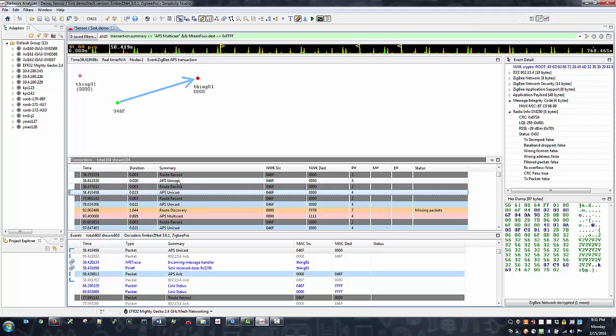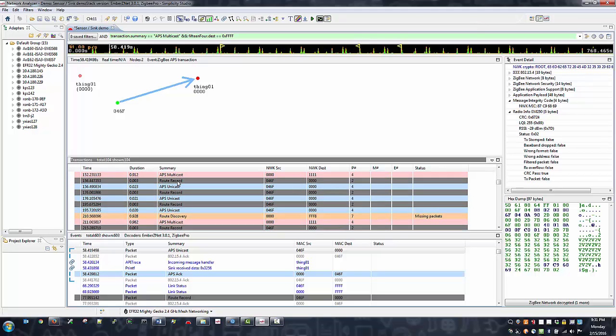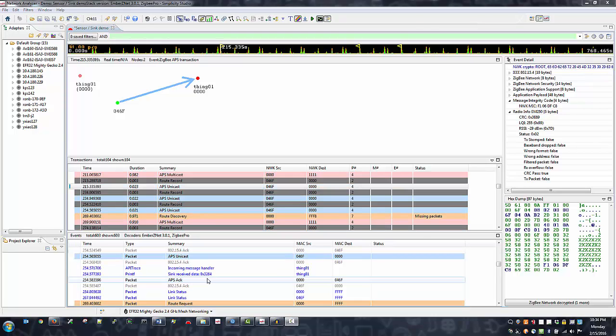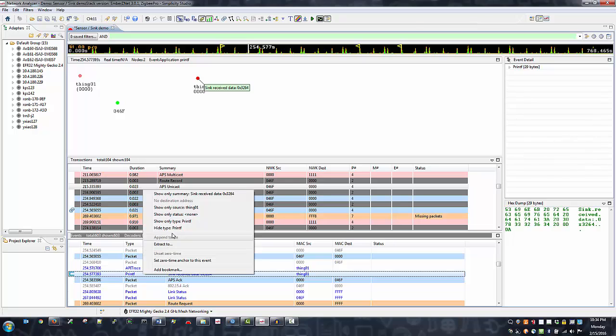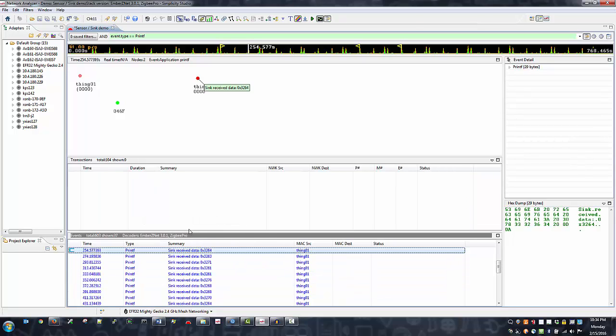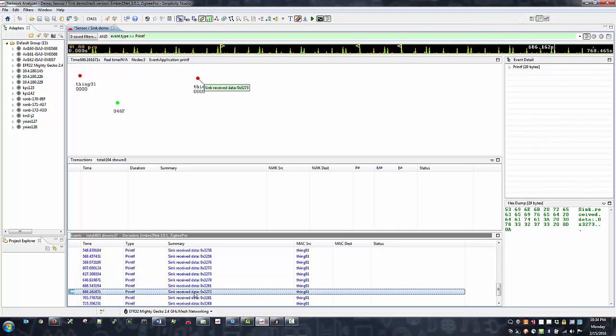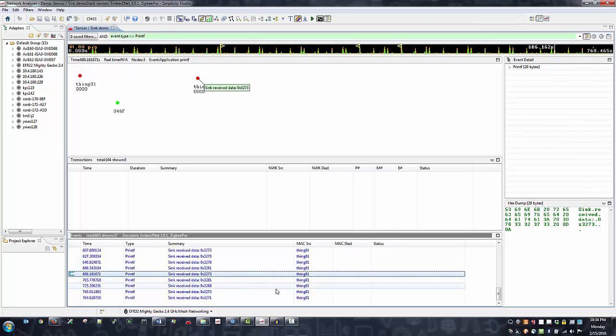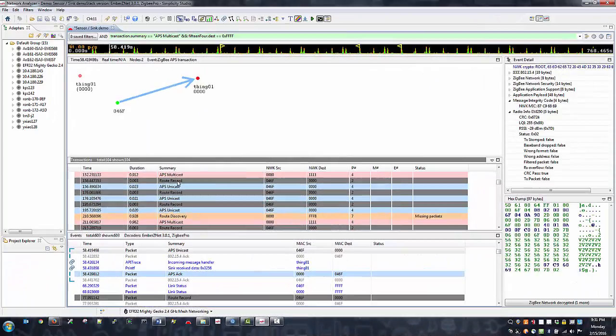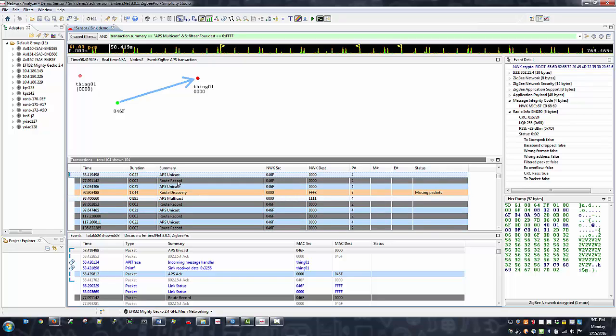Silicon Labs even provides a virtual UART interface to allow for traditional printf output through serial wire debug lines, so you can see your application's printfs among stack API and callback activity. Other critical software activities such as resets, assert violations, and stack startups are also captured in this events listing, so developers have the maximum information about what happened at runtime. This recorded information can also be a big help for Silicon Labs' experienced applications engineers when customers have questions about behavior in the stack or application.